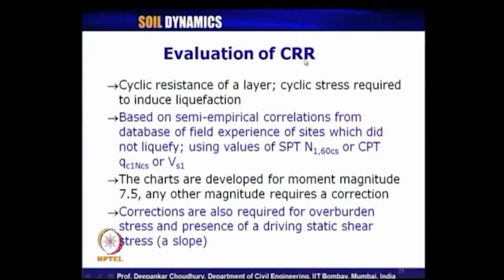Coming to another component, that is evaluation of CRR, cyclic resistance ratio. So, how much the soil has the capacity to take care of liquefaction until it liquefies or fails. Cyclic resistance of a layer is nothing but cyclic stress which is required to induce liquefaction.